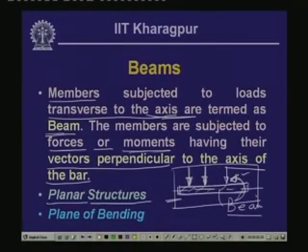In the previous lesson you have seen that when we were talking about the moment, it was about an axis which is perpendicular to the cross section. Now, we are going to discuss the moments which will be about the axes which are in the plane of the cross section. So, if the cross section is a rectangular one, then the bending or the moment will be acting about the axes which lie in this particular plane.